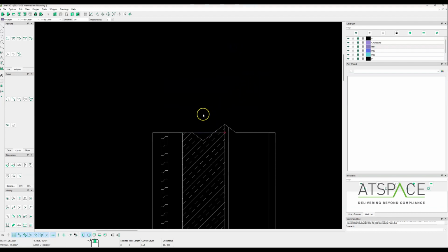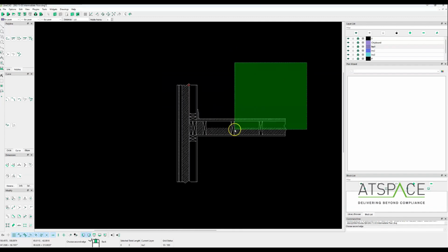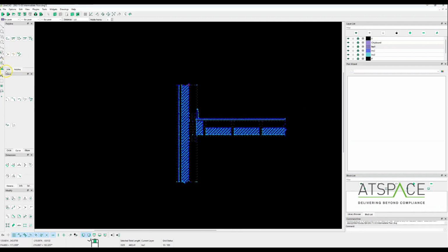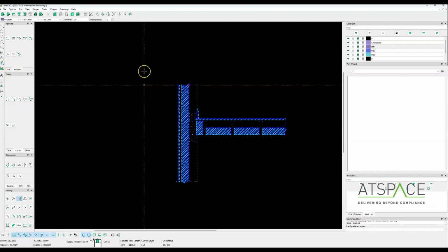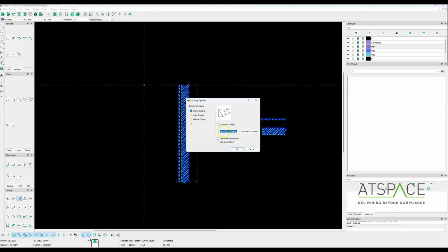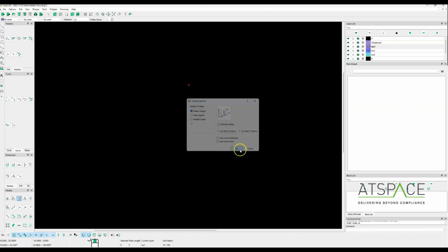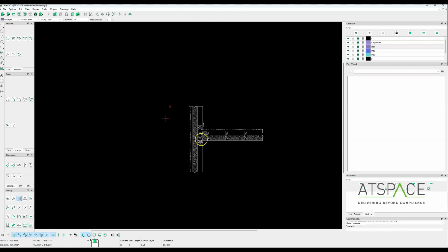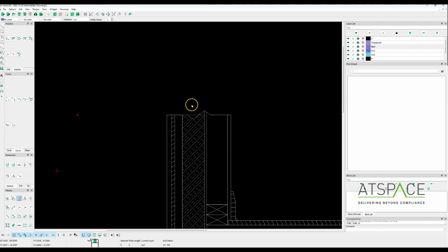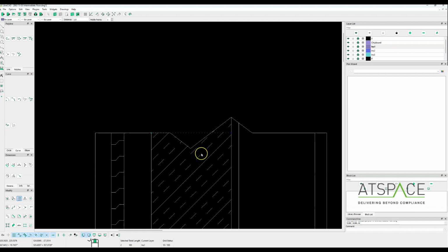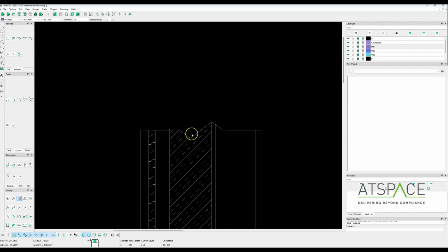We can delete, oh no, we'll leave that line for now so we can check. Then we're going to select all of these lines and then come here and scale, click anywhere. We're going to select these X and Y coordinates here and just paste in that value that we've copied from the calculator. Hit OK and make sure it's deleting the original, so that we're just going to end up with the final size that we want. So we can click on this line again now, and hopefully we can see at the bottom there it's now 100 mil, which means that we've scaled it accurately.